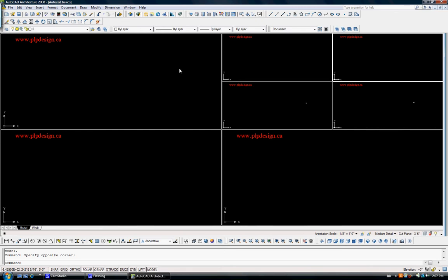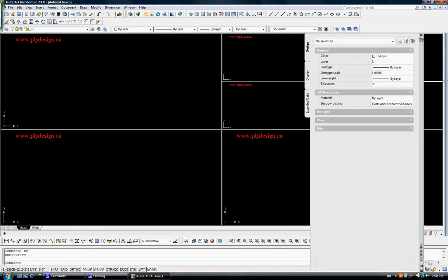I've used them on quite a few occasions on larger commercial buildings where you have to see a bunch of things at once. You want to make sure that if you're getting into multiple viewports that you do have a second monitor attached to your computer, so that other things like the modify box that I just brought up here don't cover it. I usually put all these boxes and dialog boxes on the second monitor, keeping my screen clear.